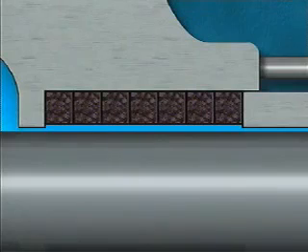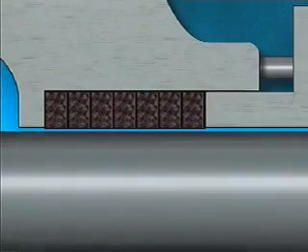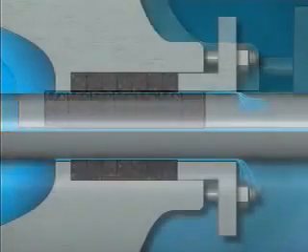During pump operation, fluid inside the pump can leak out of the pump along the shaft as it passes through the pump casing. The gland follower is tightened to compress the packing tightly inside the stuffing box. Under compression, the packing is forced against the shaft and the inside wall of the stuffing box. As the packing is compressed, the amount of fluid that can leak out along the shaft is reduced.